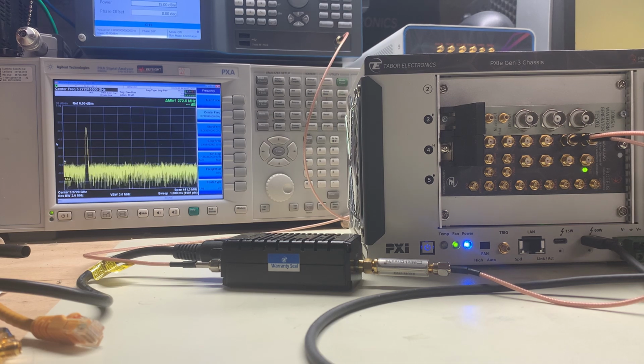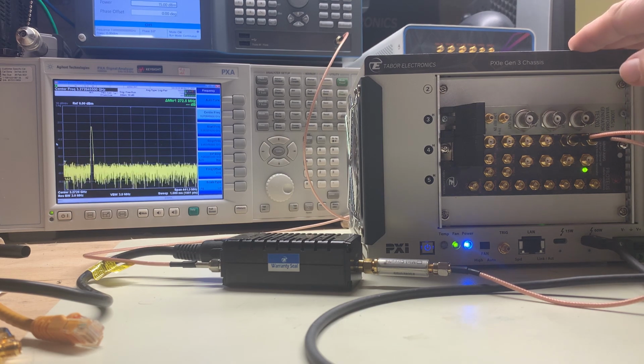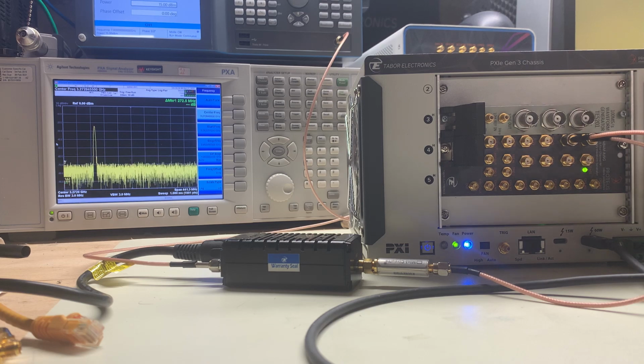This is the last demonstration in the workshop today. So I've got my Proteus unit here. I have it connected via Thunderbolt. The chassis here is PCI Express Gen 3, but the connection is Thunderbolt, so it's a little slower than a direct PCIe to PCIe Gen 3 by 8 connection that we would have, but I'm only using a laptop for the purposes of this demonstration. On the screen of the spectrum analyzer, you can see in the background a CW signal has been slowly creeping up in frequency as I've been talking.